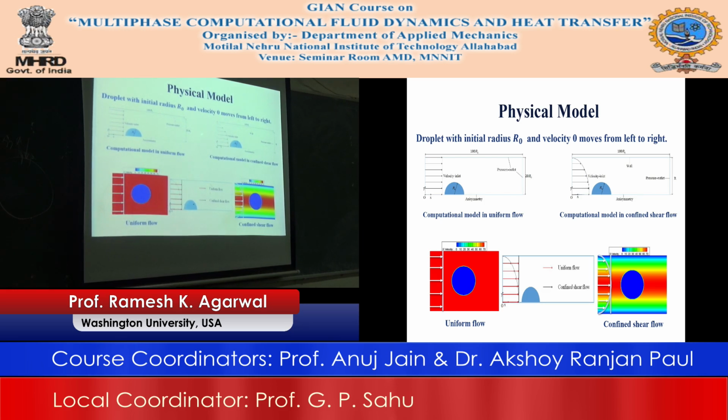Now, as I said, in practice the flow is never uniform, so you can have a laminar profile, which is shown here, or you can also have a turbulent profile, which will be a little flatter, and then you can see what the effect is. Again, this is a surface tension driven phenomenon, and we are going to assume that the flow is laminar, because the Reynolds number, even in an internal flow in this case, is much lower, around 1000 or even less. So it's purely laminar flow.